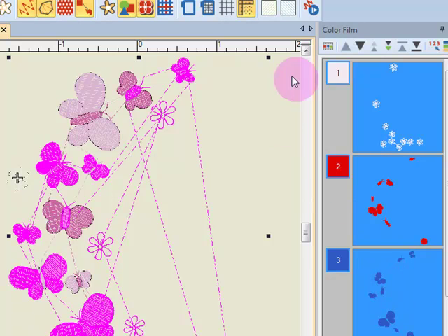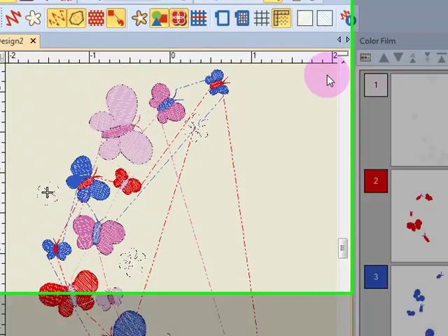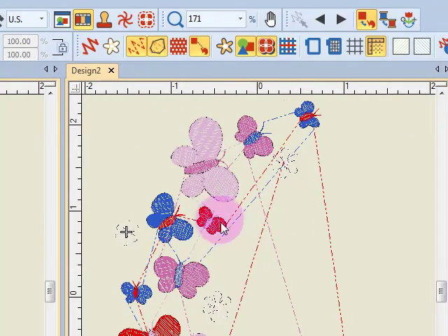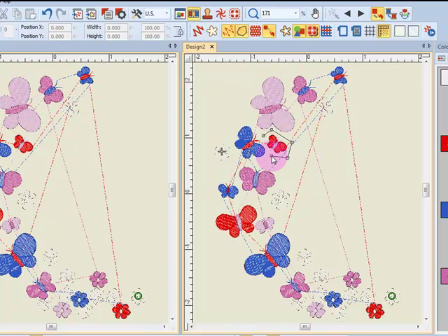If I have a complex shape that I wish to select and the bounding box isn't easy to do, to select just parts of a design, there is the Polygon Select tool, and I can click around in and out between an object, and when I press the Enter key, only that object will be selected.